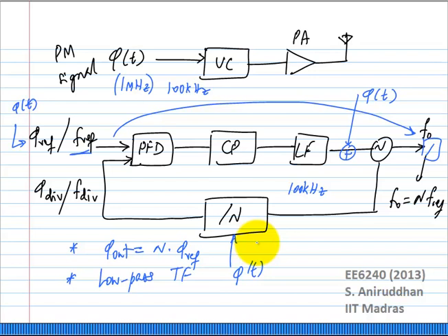Okay, so there are many cases where you have a fractional divider where you are actually able to change the output phase or frequency with a very fine step. Maybe the signal has only maybe 12 bits or 13 bits worth of data, but you can actually go to maybe 18 bits or 20 bits easily to select the frequency or phase of the VCO, of the PLL.